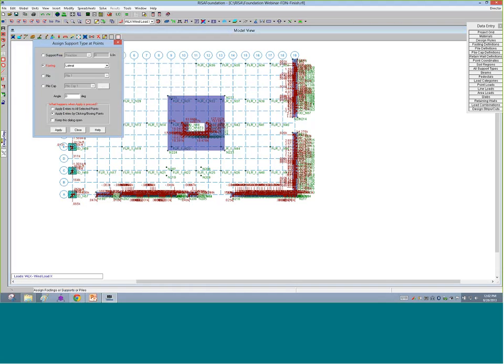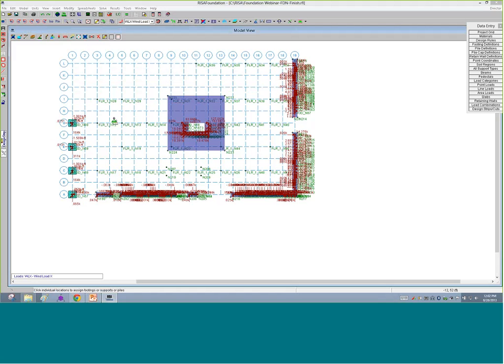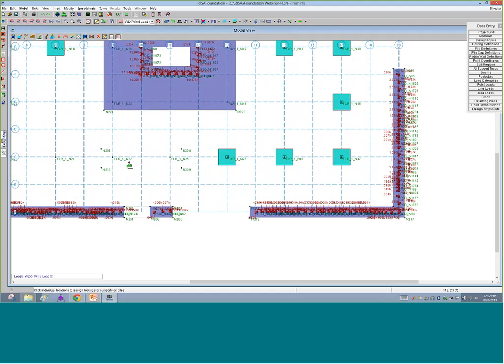And now for the other ones, I'm going to switch to the gravity ones, and these are going to be all footings in the area here. What's nice is it's really easy to draw footings. You just kind of rubber band your model around here. Now in this area, I have 2 footings that are together, and for some reason, I really want to combine these 2. And this is what I want to be a combined footing versus a single footing like that.